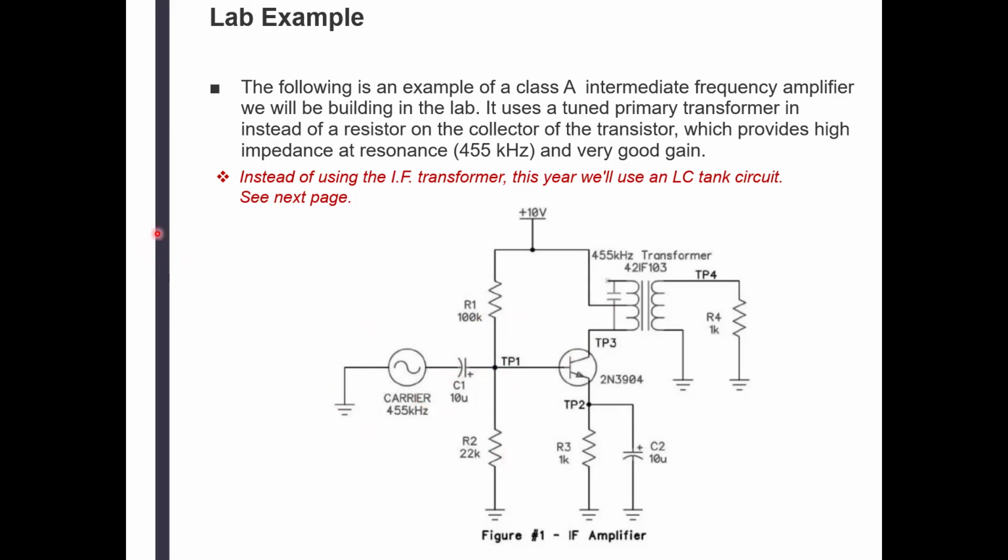Now, different channels are coming into the receiver, and that carrier frequency with the modulated signal is first transferred into the intermediate frequency, which is constant always, and then the signal is being stripped of the carrier, and then just the intelligence signal is being transmitted through the loudspeaker. Right? So let's see here.